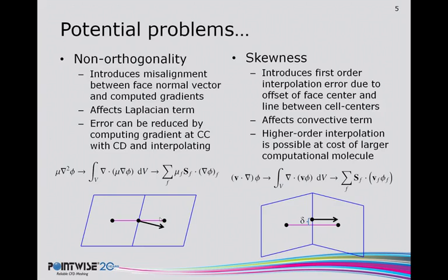Whenever you discretize and use this approximation, the gradient is approximated as the difference, in the most simplistic case, between these two cell centers, and therefore inherently the gradient is along the direction between those two cell centers. That's not necessarily where the actual gradient lies, but whenever you are using this approximation that is CFD, it's just one of the results. Since we have to compute this dot product, you can actually introduce some error because you are doing additional manipulations to these already approximated quantities, and so you can introduce error to this diffusive term.